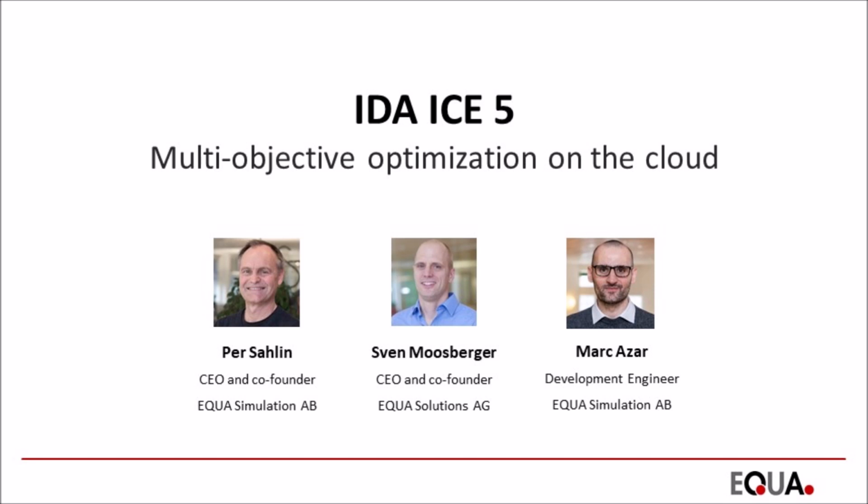The other one is that it's really designed for a limited number of cores, so it will take advantage of parallelism initially in its process, but after a while it generally switches to some steepest descent type of algorithm where it will only use one core in one experiment at a time, and this becomes very limiting, especially on the cloud when you want to use all that computational power that you have. And the other thing with Genopt is that most people, including myself, use it pretty much only with the default settings, and Genopt actually has a whole language for tuning the optimization algorithm, but if you take a look at the manual, you see that it's not so simple to select and tune that algorithm in the best way. So I hope that was the answer to that question.